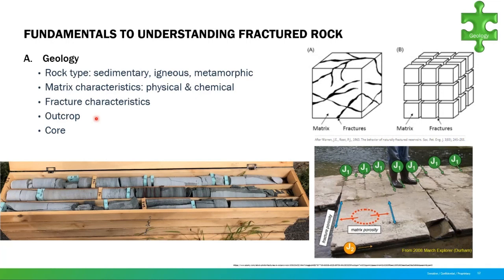And what we like to do is really try and find two components to study when we're thinking about geology. Outcrop, while especially in the Northeast, we don't often have the opportunity to have outcrops, but that doesn't necessarily mean there is no information to be gained. It's important to look through the research. There might be an open pit mine nearby that you can get access to, and look at the outcrop there, or in this case, near a lake bed, the rock of interest was outcropping, and you get an appreciation of the vertical fractures and the strike and dip of those fractures. And of course, the rock core itself.